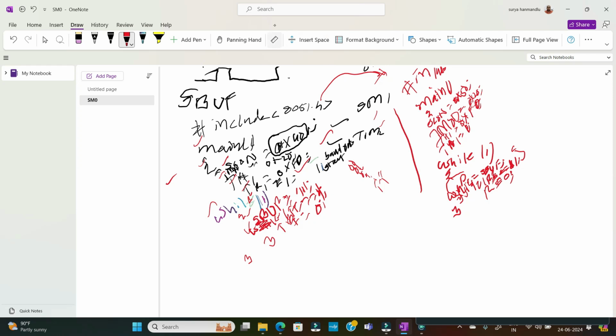And here also the same. Let me take a black pen. So in main, here also we include the same header file, same steps. Main method, of course, is very important in all C programs. In the main method, the first four steps are common. We select SCON, we select TMOD, we set the baud rate, and we start the timer. Then in the while(1) loop, instead of writing SBUF equal to H, we don't know what characters we are going to receive, right?